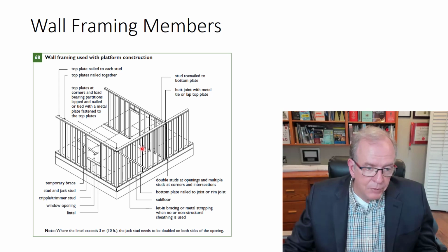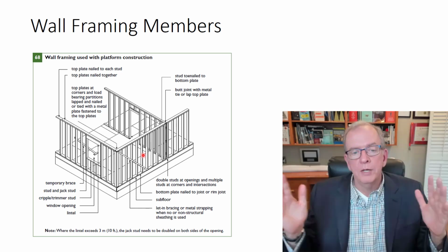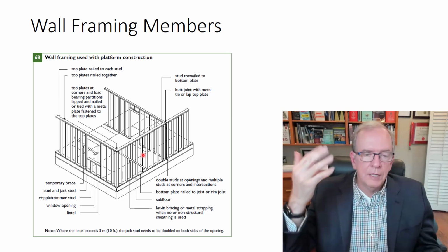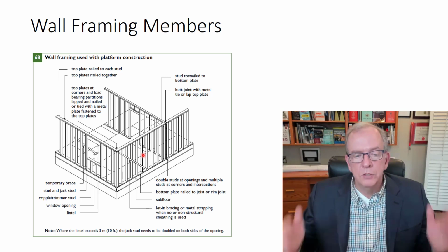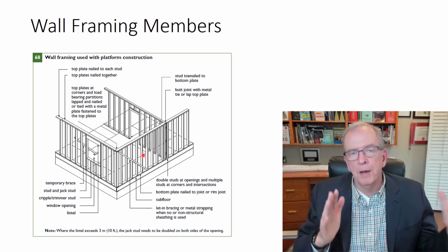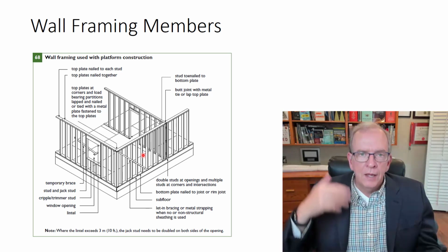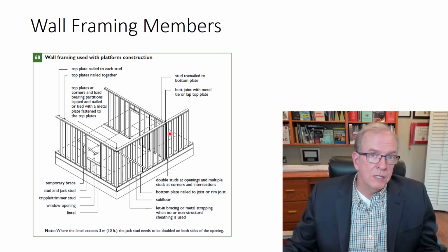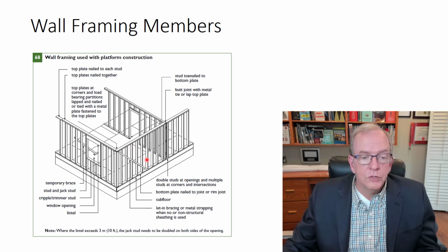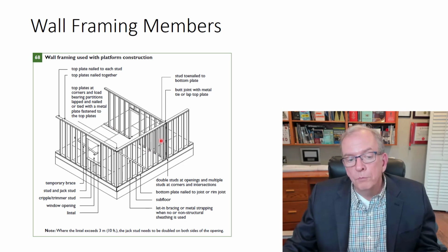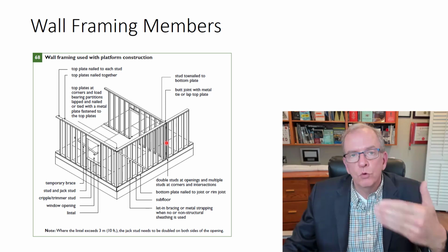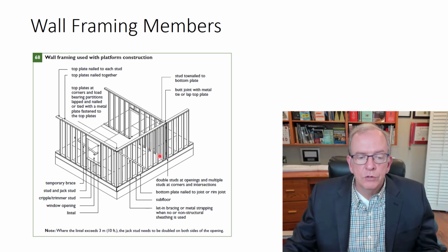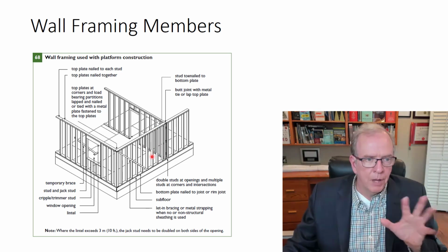And like I said, the spacing between your studs could be 12 inches, 16 inches, 19.2. 19.2 has gained popularity depending on the building code requirements because you can use fewer studs and you can buy standard spacing insulation for that. And using fewer studs, that's less expensive from a lumber perspective, but it's also a good thing because there's less thermal bridging of the cold of the warm moving through to the cold. So warm travels towards cold, and it'll travel much easier through a 2x4 or 2x6 than it will through insulation. So those are some other little tips here.